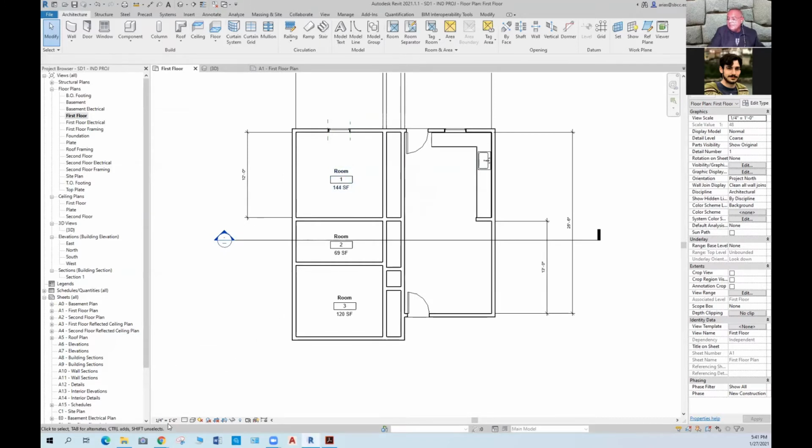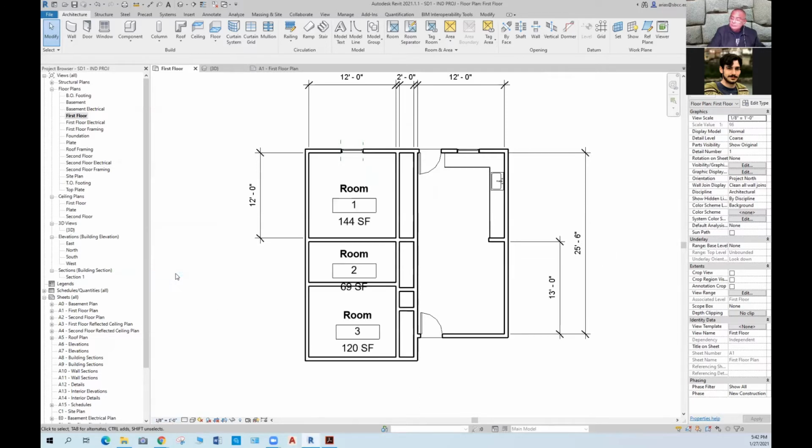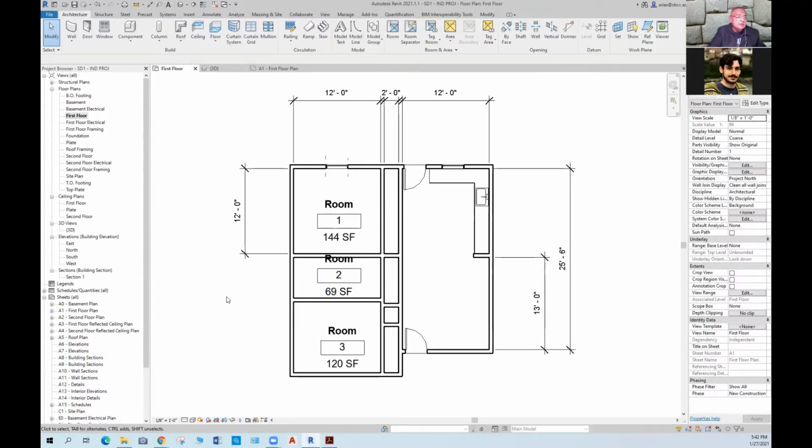Now see what happens if I modify the dimension, right? Maybe I don't need a 1/4 inch scale. Maybe I want to print this at a 1/8 inch scale. See what happens to the text. Now, apparently the text became larger, but that's not what's happening. What is really happening here is that the building became smaller. The scale of the building is smaller, and so the text remains the same. But because we made the building look smaller, the text seems larger, right?